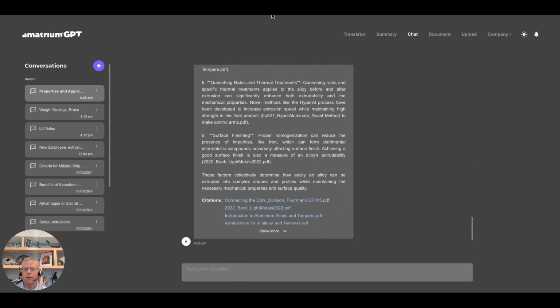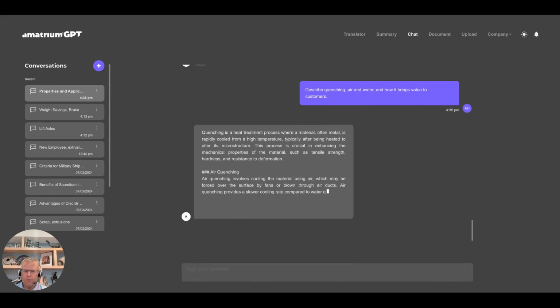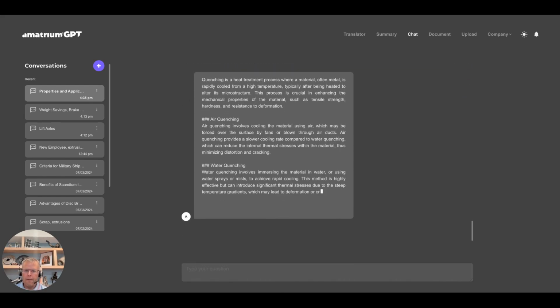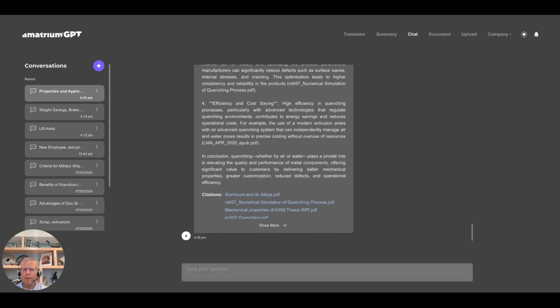So another good answer. Quench is an area that's really pertinent to high quality extrusion. So we can ask a question like, let's investigate that a little further: describe quenching, air and water, and how it brings value to customers. Again, we're always focused on the fact that you're doing process engineering, but we're developing a product for the customer. And it gets into the details of air and water and mechanical properties and efficiency and so on. There may be, of course, with every process, some level of scrap. So we can dig into what the leading causes of scrap are.